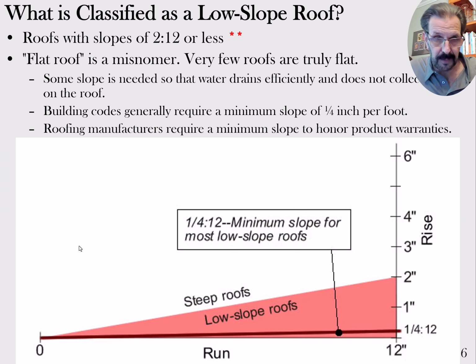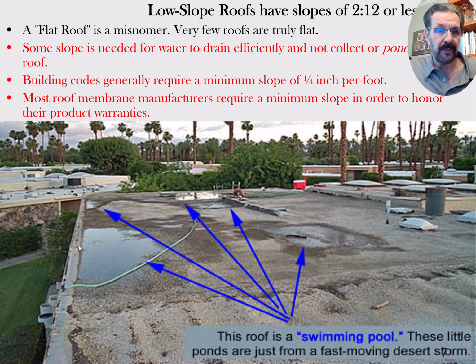Okay, so that's enough about that, and enough about this picture. This picture shows similar text, but it's showing you a built-up roof with the tar and gravel roof. I still call it a tar and gravel roof sometimes, but it's really melted asphalt in layers of paper, and then they put the gravel on top as a ballast, and it helps to protect it from the ultraviolet rays deteriorating the tar and materials on the roof.